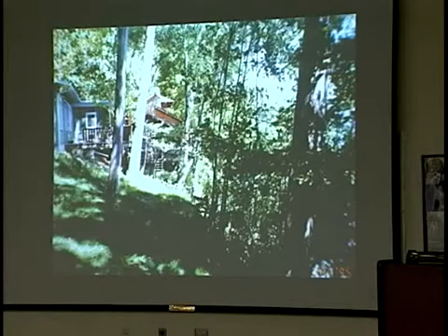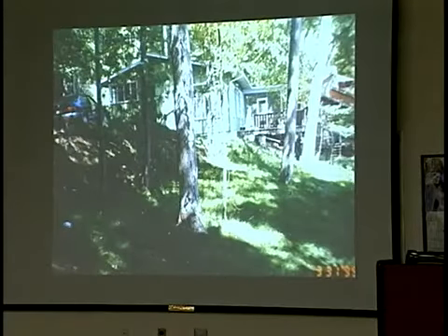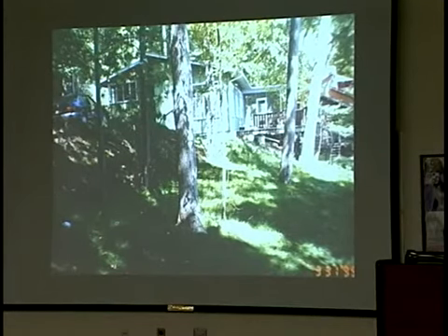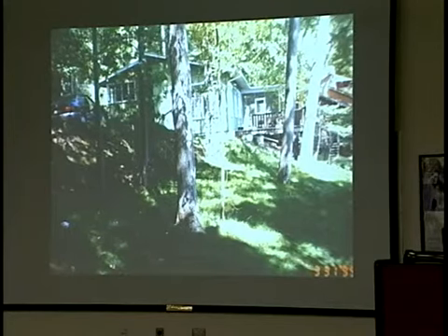But look at the grass growth. Again, I'm getting nutrient uptake. You can see the lake is way down over the embankment here. I'm getting nutrient uptake. The only thing I recommended to them here, they ought to bring a lawnmower down, keep the grass mowed. Once lawn grasses reach a certain height, they go dormant. They're not drawing up many nutrients anymore. If you mow a lawn area, it keeps growing, it keeps drawing up nutrients. So I recommended they get a lawnmower.